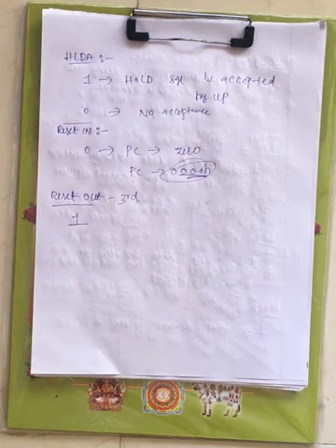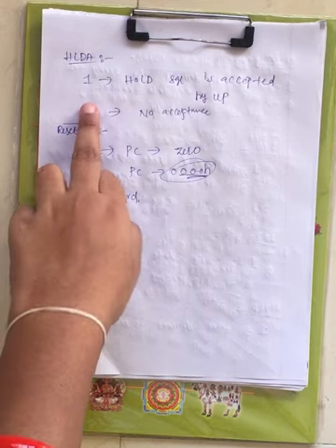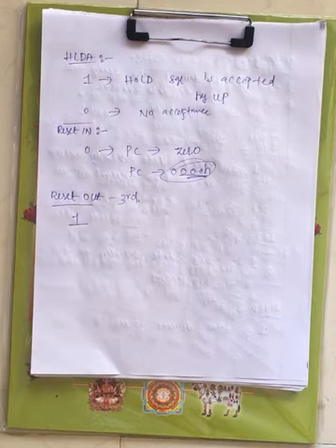When it accepts the hold signal, it provides an active high signal over HLDA, hold acknowledgement. Acknowledgement is nothing but acceptance. When the hold acknowledgement signal is 1, it indicates the hold signal is accepted by the processor. When it is 0, it is not accepted.